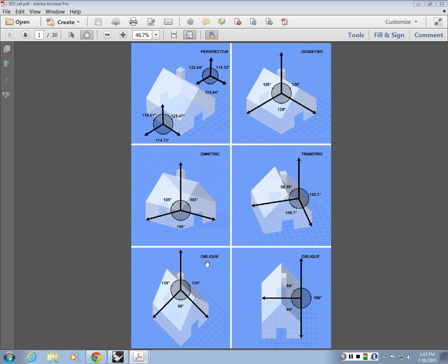So in oblique, since the plan is more acute, you show more of the plan compared to the walls. But in isometric drawing, the emphasis is more equally distributed. So you're showing as much information or emphasis on these faces as well as the plan, right? So it's more of an overall general outline for drawing orientation. So what would be in the diametric, you think? If you look at the diametrics, the 150 is aligned to the plan, right?